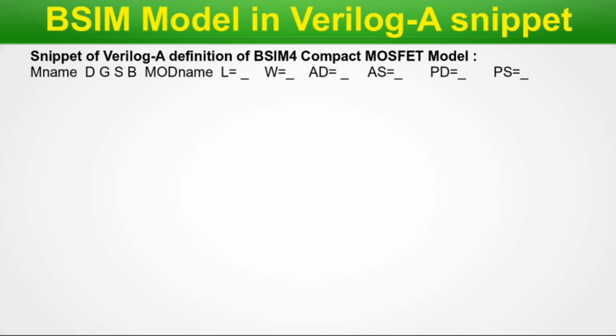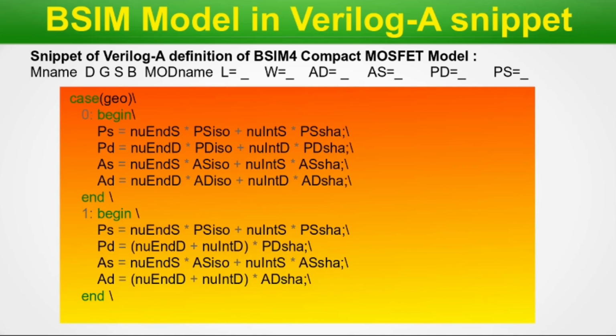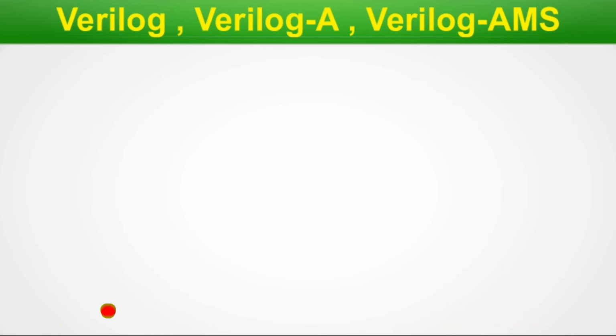So let's see a snippet of how Verilog-A is used for the calculation. Here a case statement is used for calculating PS, PD, AS, AD. This is just a snippet, so the entire code is huge. This way, Verilog-A compact modeling helps to generate the MOSFET model cards for our latest-day SPICE models.